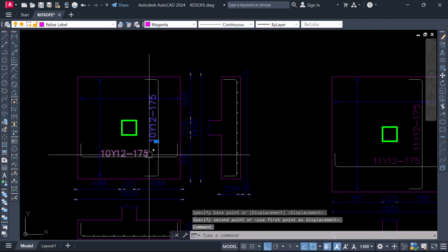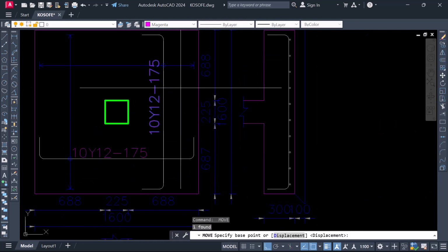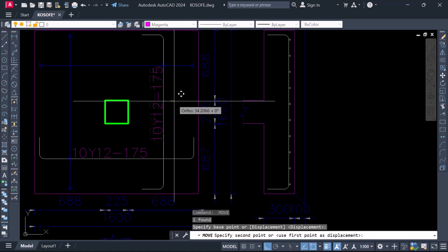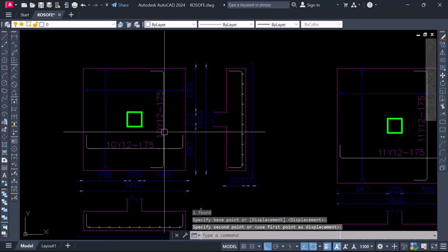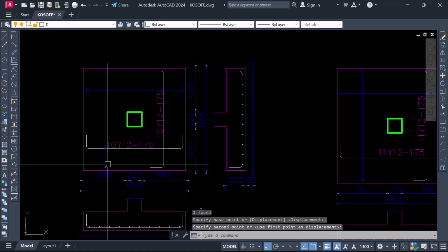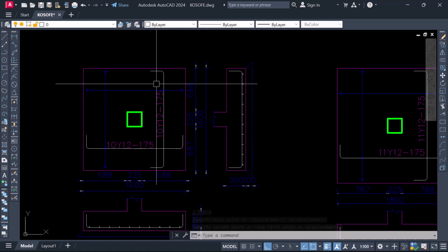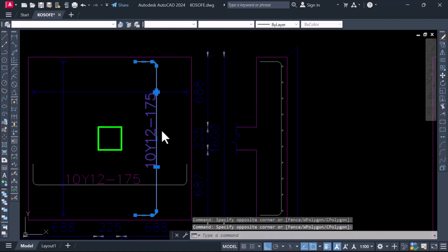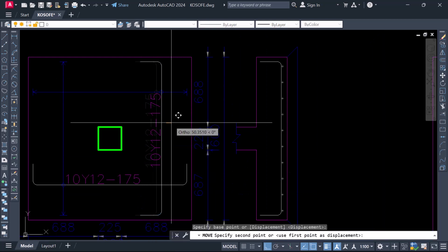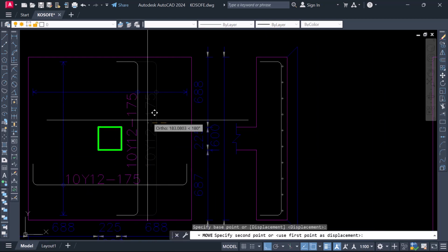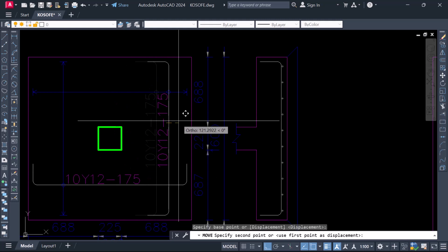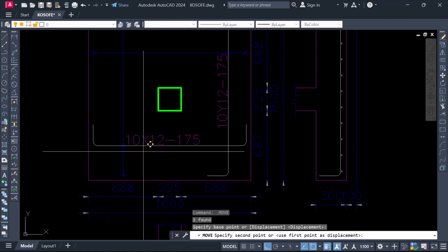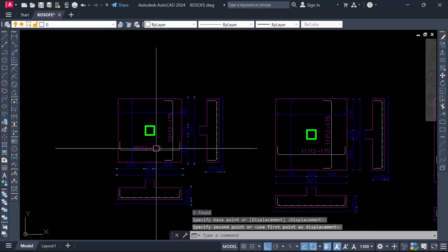Simply because you can see, if I push this text down, if I move it down, you can see it's almost clustering with this. So what I'm going to do is push this to one side. I'm going to highlight the text and highlight the rebar. Okay, so I'm going to move it a little bit from this other one. I'm going to move it down. You can see it has created a little space. The same thing here, I can also do by moving it down. You can see that they've separated.